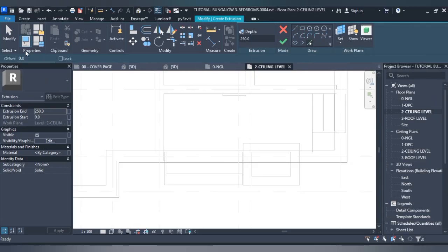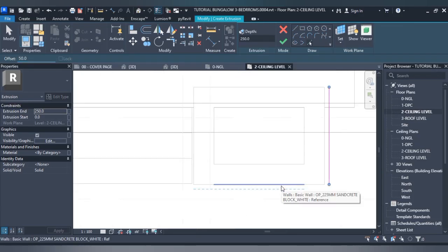So if you notice, I did not go back and start clicking on model in place. It makes you have a whole lot of caseworks, and then at the end of the day it ends up lagging your work. So you can just have every single casework you want to do under one particular casework. It just makes things much easier for you.